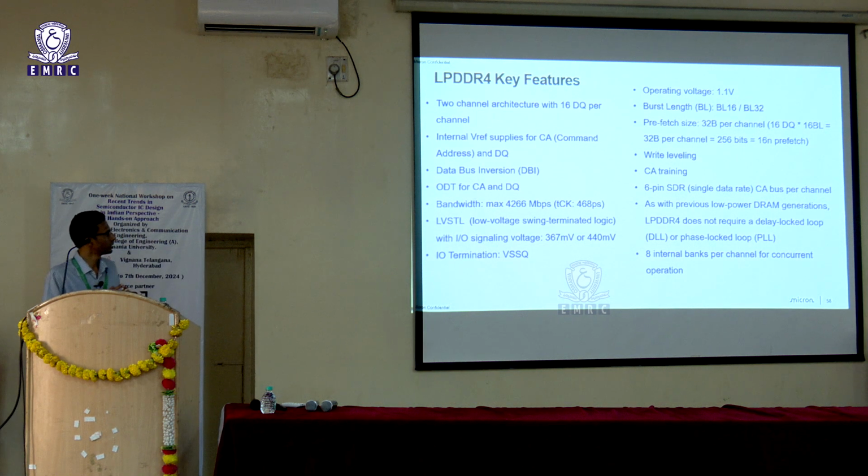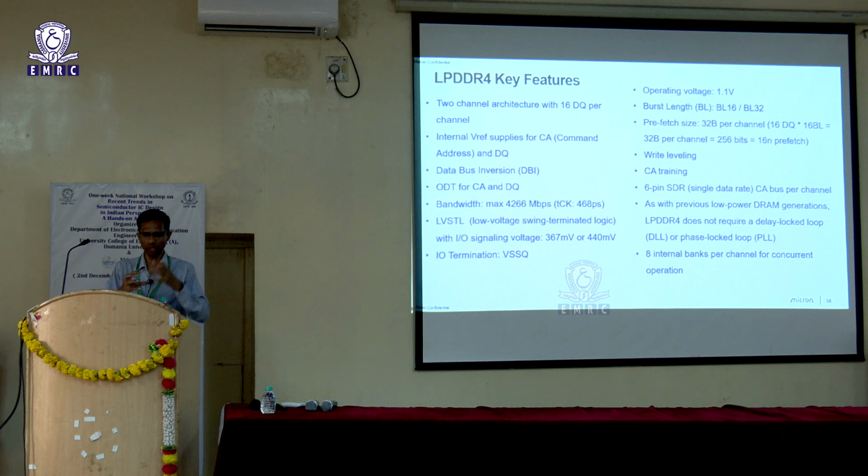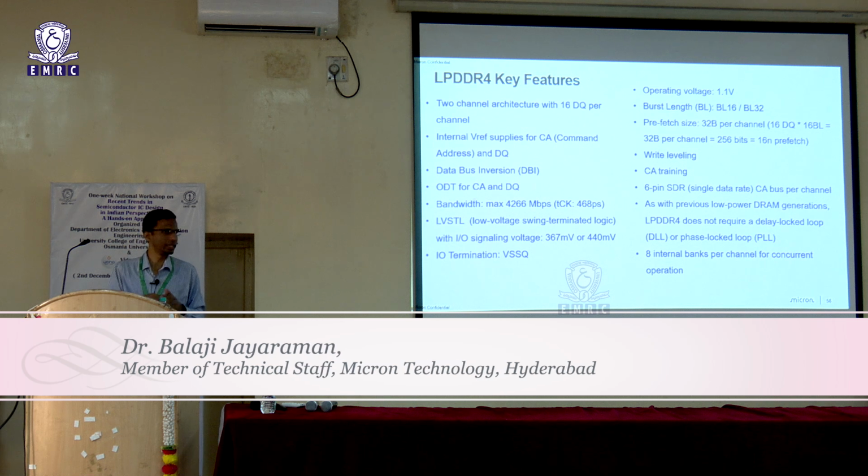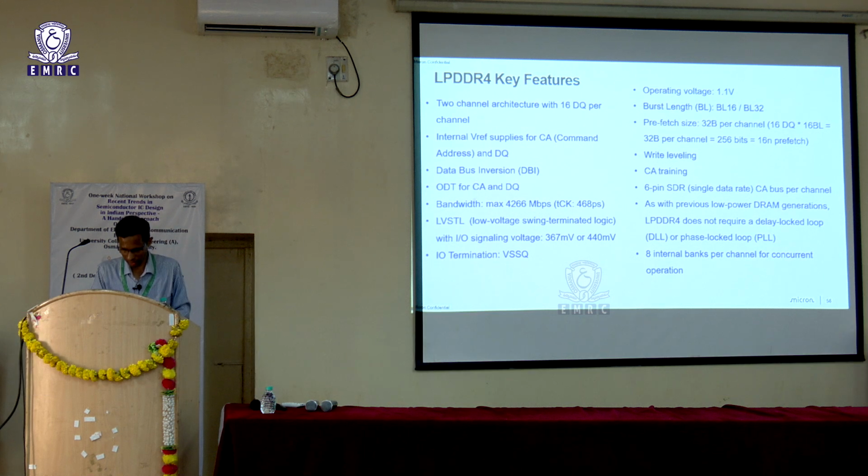Write leveling is again part of your training. As I said, when you are interfacing a DRAM chip to an SOC, the clock comes in and also the data comes in. It is our responsibility to latch the data at the clock edge, and if there is a skew between those, you will not be able to capture it properly. So internally you will have to ensure that the clock comes right in the middle of your data eye. That is done through write leveling schemes.